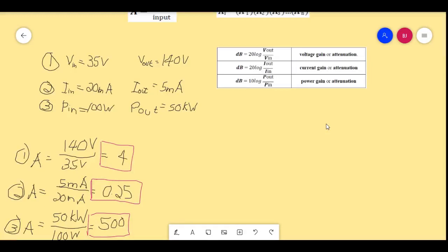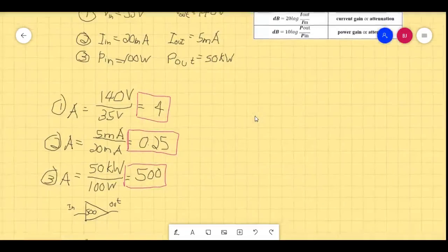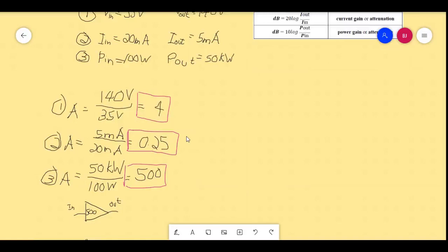The reason that they convert terms like this into decibels is that there would be times that the gain in absolute terms would be very, very small, like, I don't know, 8 to 9 decimal digits, like 0.000000135, something like that. Or it would be very large, like around 3,900,000. So it will be using lots of digits to represent it. Okay? For the same reason we convert values into engineering notation, to shorten them and make them easier to the eye and easily understood by someone who is looking at it, we also use decibels with the same regard.